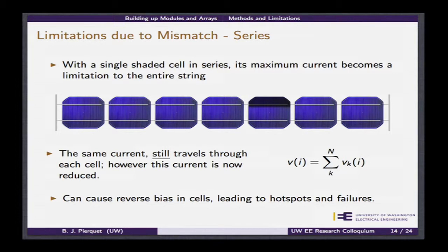That means it's going to start to push more current into the cell instead of out. What that will cause essentially is localized heating. Because these aren't perfect materials and there are defects, it's going to force the current into a very small area, likely heating it up and damaging the cell, and then causing a permanent issue, even though what may have been afflicting it was temporary.